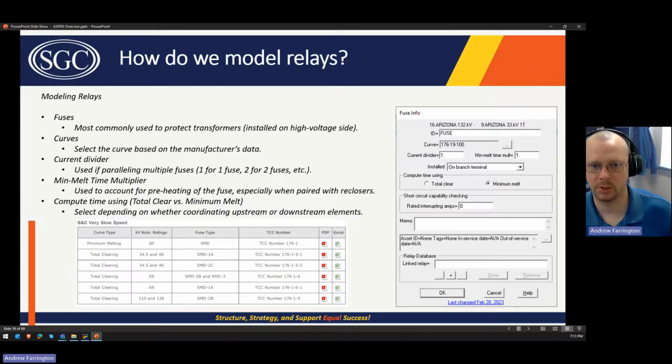So they commonly say, okay, for a 5 MVA transformer, we use this fuse type, and they standardize on that because it helps them with their distribution coordination and their other protection coordination for the transmission lines as well. So usually you just have to find your particular make and model, and then the continuous current rating for that curve, for that fuse.